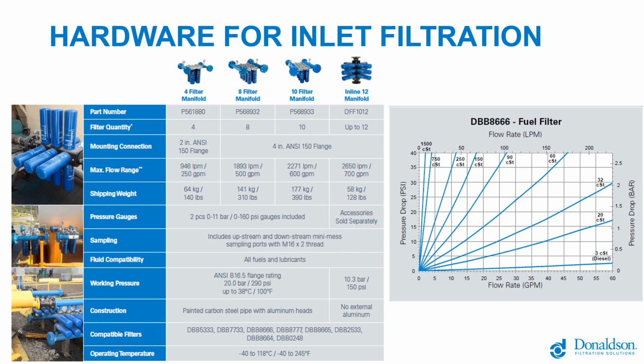Well, consider again our 250 centistoke and 1500 centistoke behavior of the previous filter. This is the next tighter filter in the product line that fits on these heads. And here is your 250 centistoke pressure drop curve. And you're back down at the same temperature at 50 degrees Fahrenheit. You're back down to 2 gallons a minute per filter.